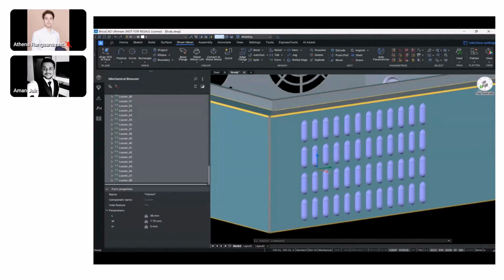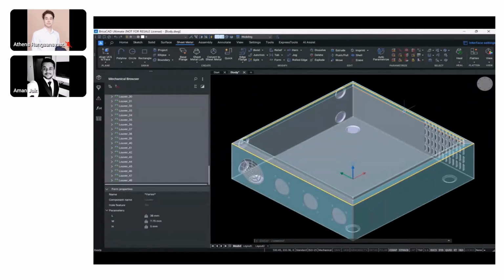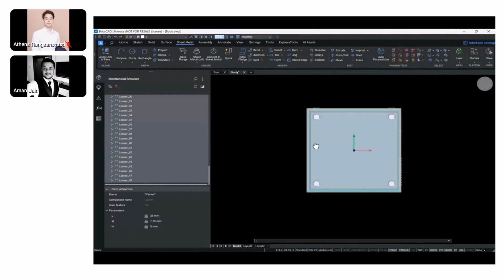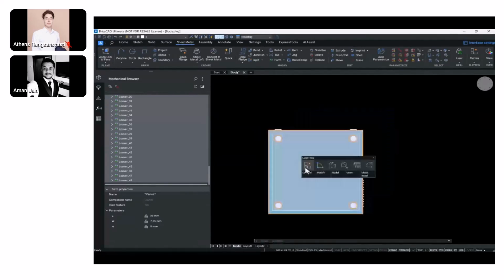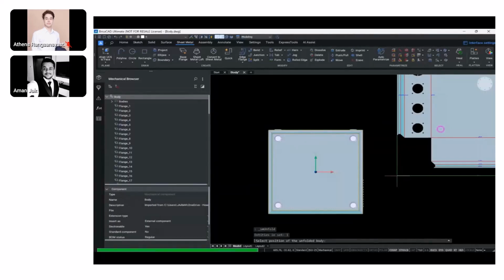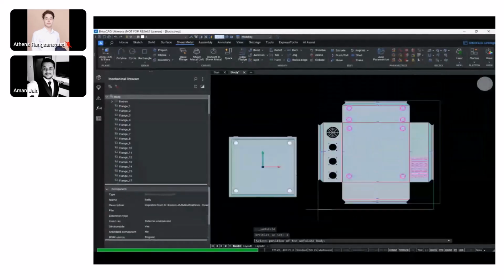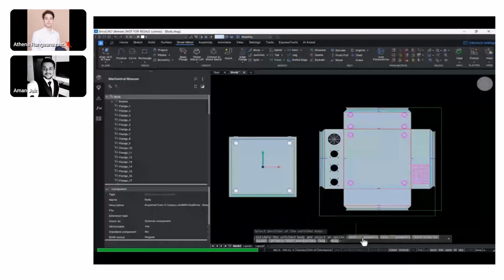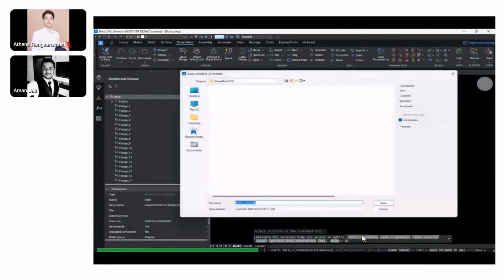So that's how I'm able to replace the existing form features that could have come from any of the 3D modeling software. And then finally, of course, the most important thing is whether we are able to unfold this entire body. Yes, so we can do it. We can unfold this body completely. And the representations are as per design standards that are used in any of the companies. So let's say even for the form features that you can see, those are the very accurate representations that we get for the louvers, for the other form features that are present, right?